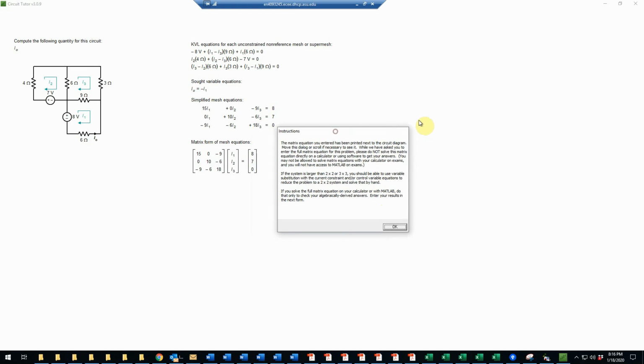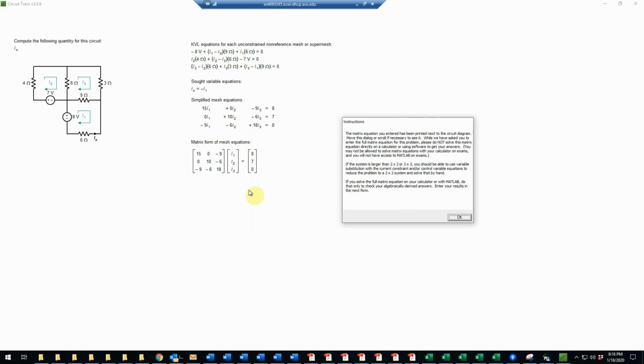And now the goal is to solve these equations, and of course our ultimate objective here is just to find I0, which requires knowledge of I1. Now we're going to use Gaussian elimination here, since we have only KVL equations. No obvious substitutions are possible, so we're going to solve this using a Gaussian elimination process, which is a way of doing a 3x3 system or a larger system.